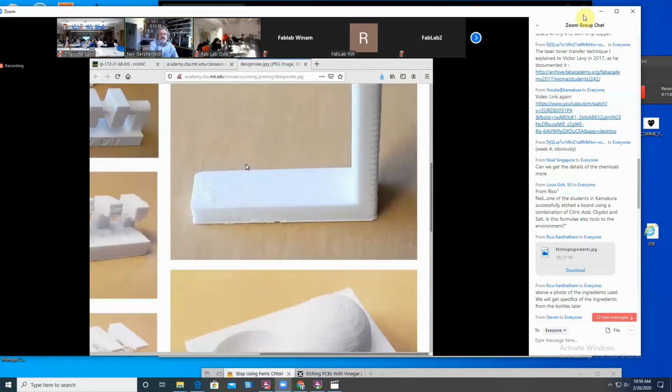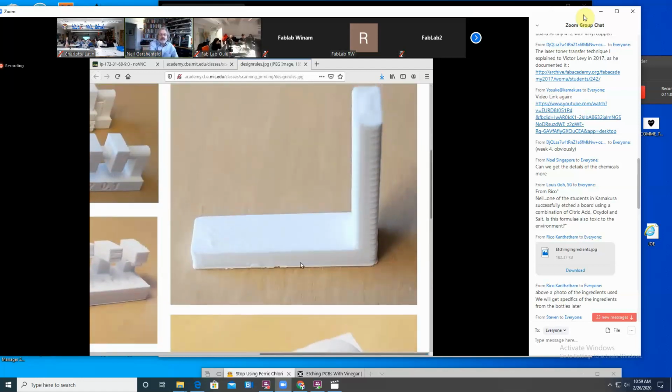Then most of these are anisotropic. So in this part, on this beam, the filaments go that way. On this beam, they go this way. And so if you pull in tension in that direction, you're pulling in the long axis of the filaments where they're stronger. If you pull in this direction, you're pulling where they're bound, and that'll fail more easily in that direction.